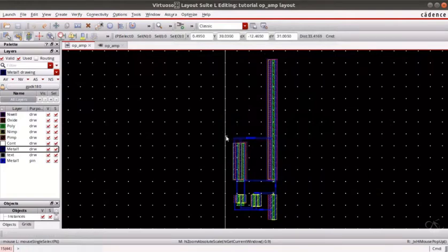So this is not yet a very optimized design, I can say. Coming to the advanced VLSI design, we will try to minimize the wastage of area, and also since it is an analog block, we will provide appropriate shielding so that it does not get affected by the circuits around it.